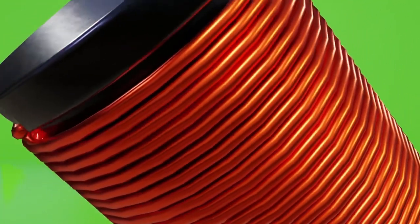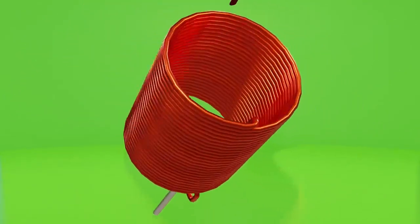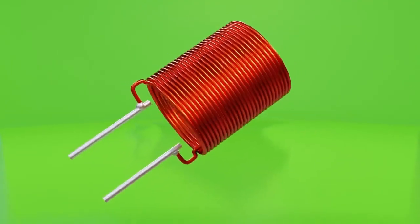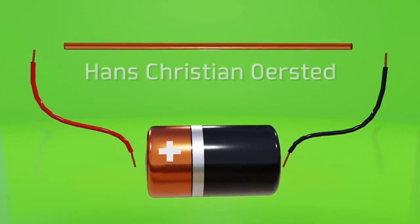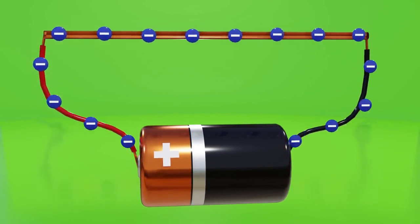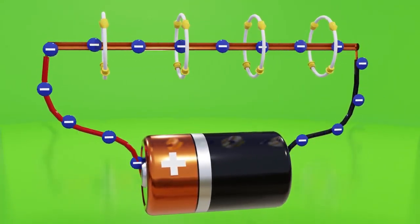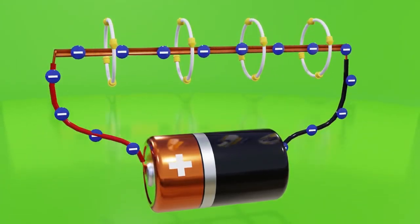Inductors work thanks to their spiral shape, which takes advantage of a mixture of three rules or laws that relate electric currents to magnetic fields. So let's analyze each of these separately, and then we will see how they work together. The first of these was discovered by Hans Christian Ørsted, and it states that an electric current, namely the movement of electrons through a conductor, is capable of generating a magnetic field. And it is because of this dependent relationship between both characteristics that the term electromagnetic field is also commonly used.